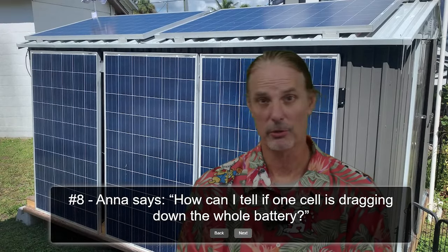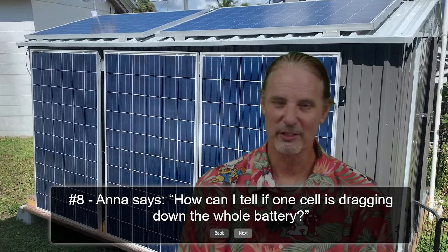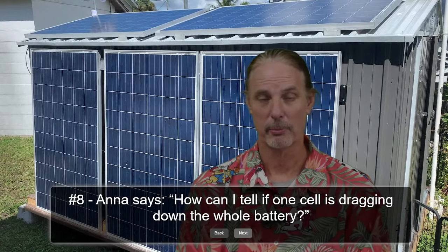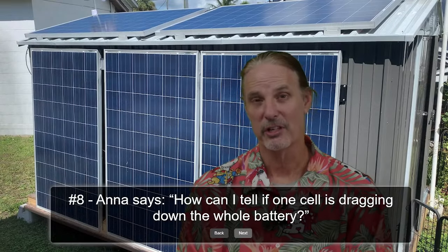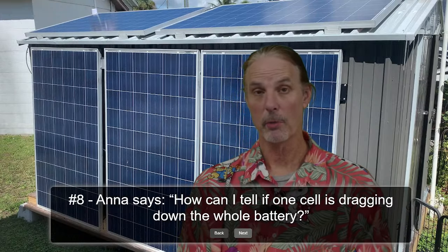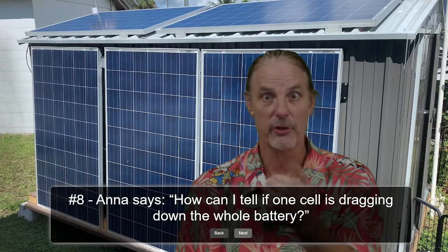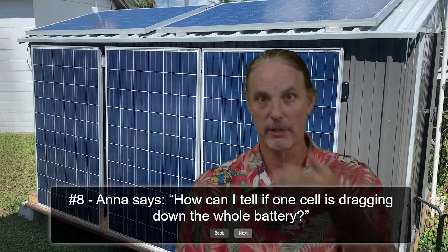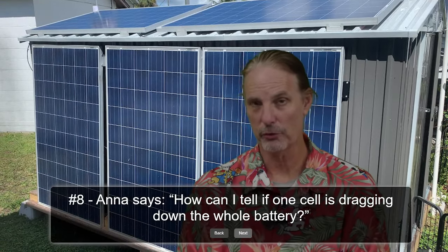You can replace it with a cell that's of equal or larger size, and larger being relative in nature. I don't mean go in and take a 100 amp hour cell and replace it with a 300 amp hour cell. I'm talking about take a 100 amp hour cell that has a year of degradation in it and replace it with a new one. It will be brought down to equal the other X number of cells in that pack. So you're not going to get 100% out of that cell, because now it is gone past the point of being useful at that point.